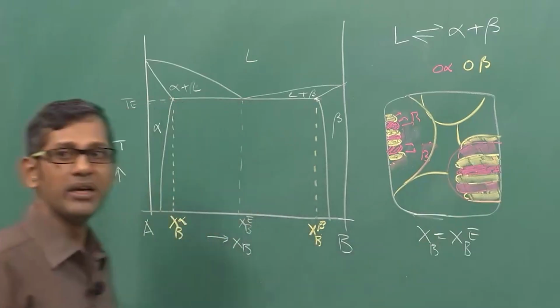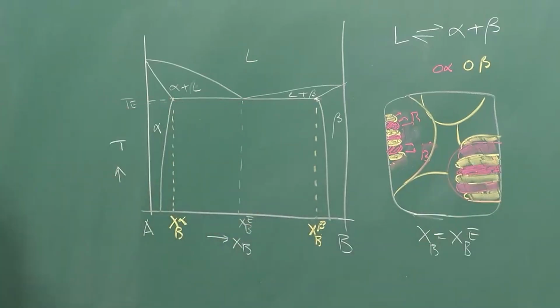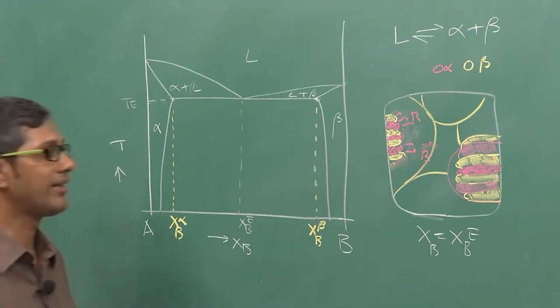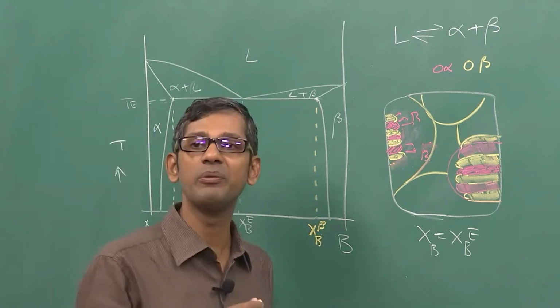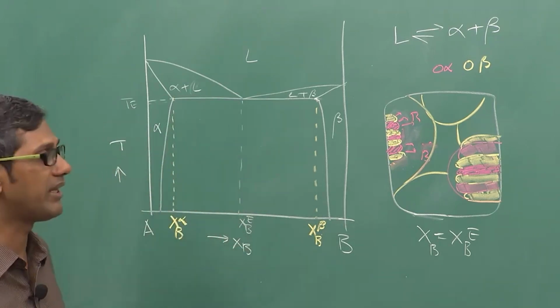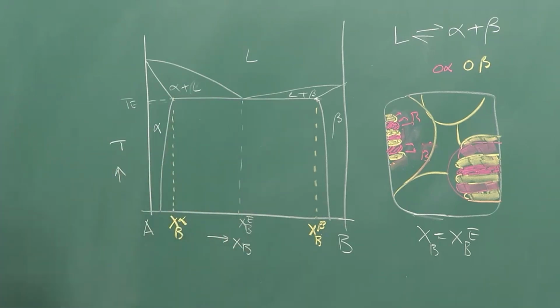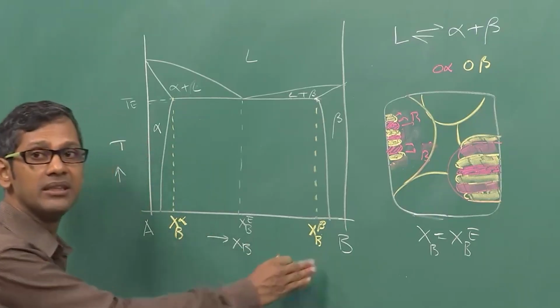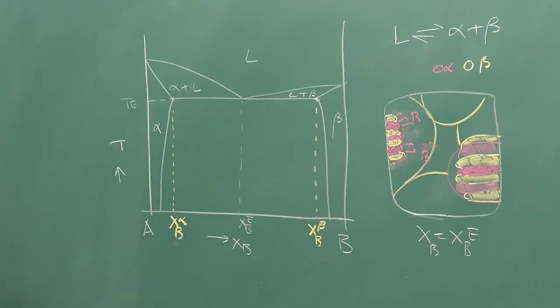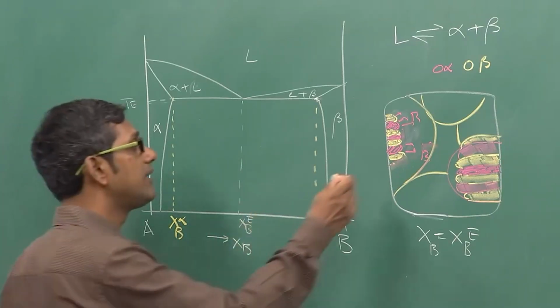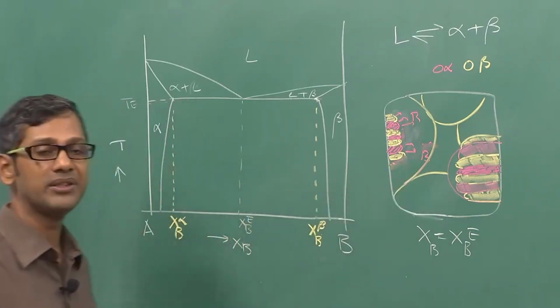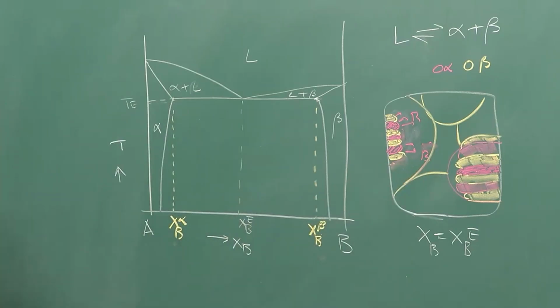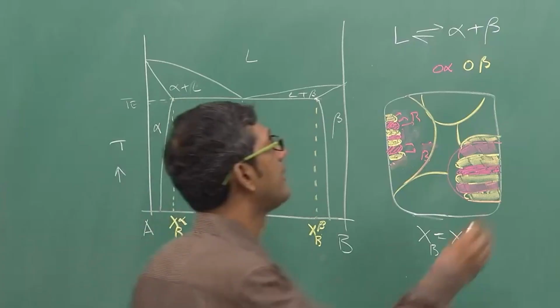Now the things will be a little bit different when you go from lamellar to rod or even nodular or acicular eutectic, but the mechanism will remain the same. The mechanism is not going to vary, because in all these eutectic phase diagrams one phase will be rich in A, the other phase will be rich in B. So it does not matter whether you are forming a morphology like lamellar or rod, the rejection of the solute in the liquid and the side regions will be very important. The important lesson which you observe here is as compared to a dendrite.